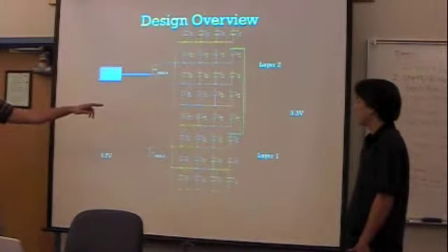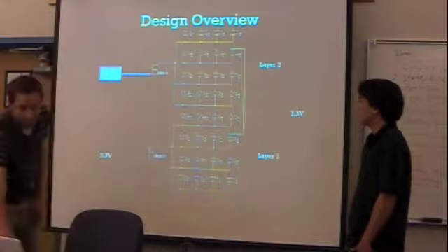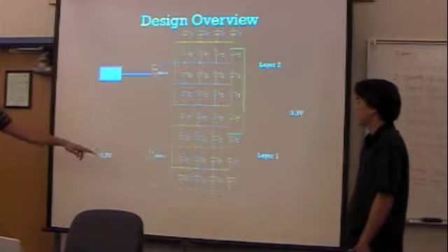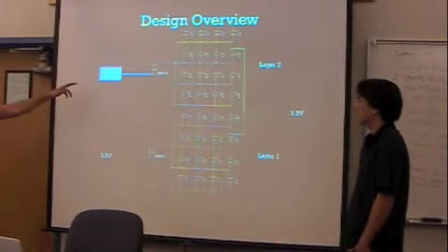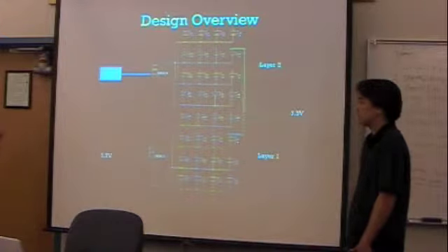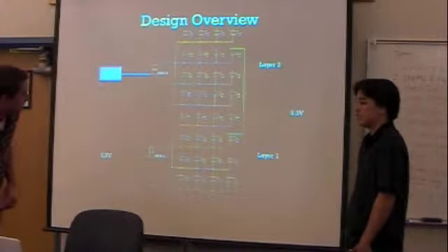And then if you put a voltage high enough for the LED to activate, you could open up this side and basically get current to flow through that particular LED, and it flows through this layer, not the layer above, because this layer is off. So that's basically the idea of controlling which one you're going to use by not having 67 outputs, because we only have 20 outputs right now. So the multiplexing idea is to tie all the cathodes together and all the columns together to greatly reduce the number of outputs, because as the cube grows, it just becomes enormous.